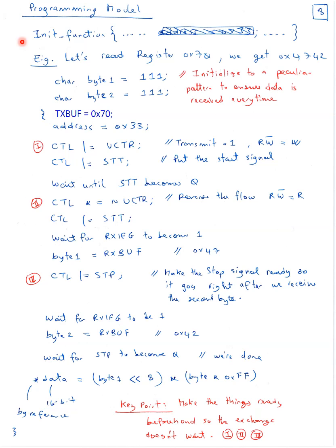We're gonna specify that the I2C module is actually working in I2C mode, because that same module supports multiple protocols. That's kind of similar to the initialization function of the UART. So once we configure it and it's running, then we can start doing communications.